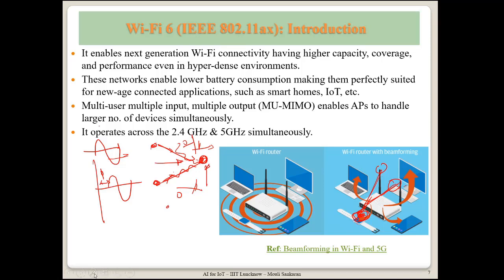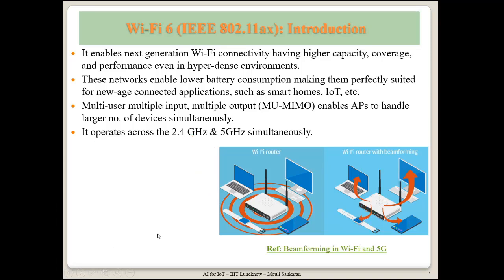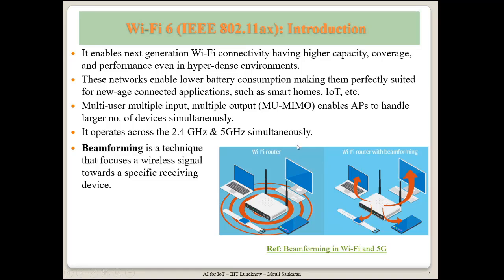A single antenna is omnidirectional, whereas if you have multiple antennas, they can be directional, and by that you can enhance the signal as well as remove the interference, so that other devices also can communicate with some other transmitter in the same frequency because they are not overlapping. So that is the advantage of MIMO technology, which is multiple input, multiple output, having multiple antennas.